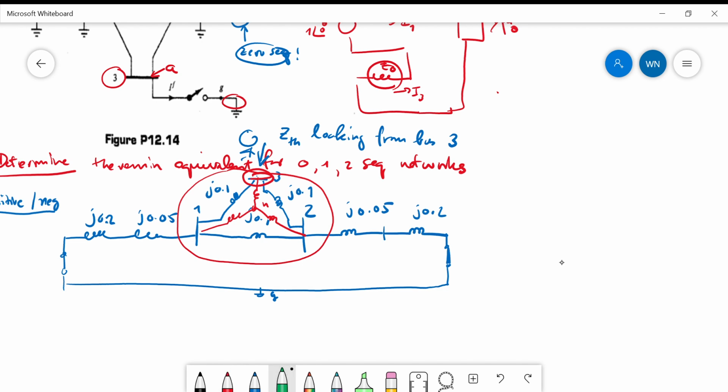If you want to find the Thevenin equivalent from circuit theory, what you have to do is like this. You have the ZTH here. You deactivate the sources, which we have done already. You deactivate these two sources. You want to see the ZTH like this.